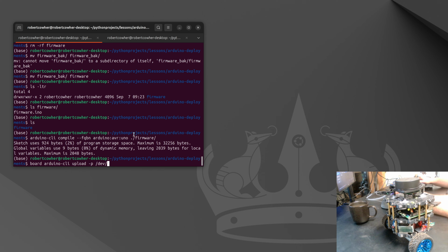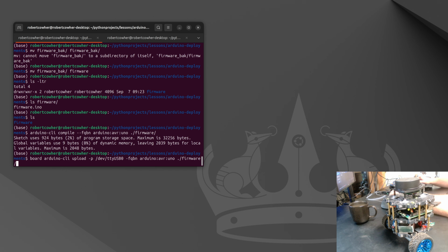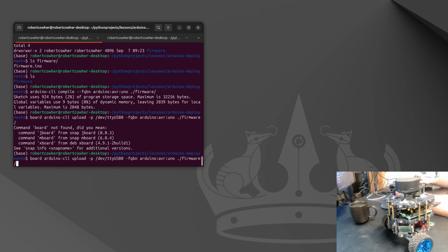So, all right, we've got arduino-cli upload /dev/ttyUSB0, FQBN arduino:avr:uno, and then we're going to do firmware. Okay, and I missed something here.